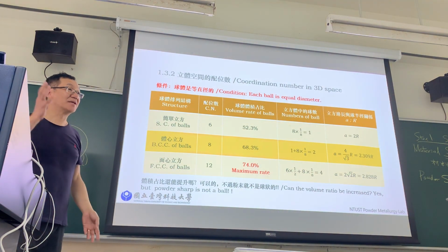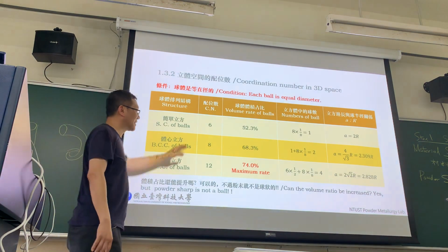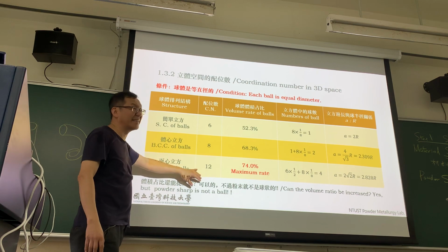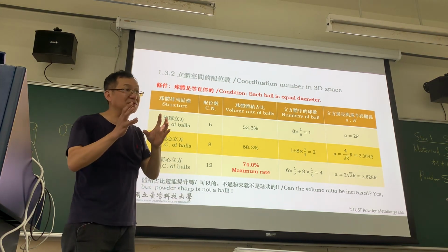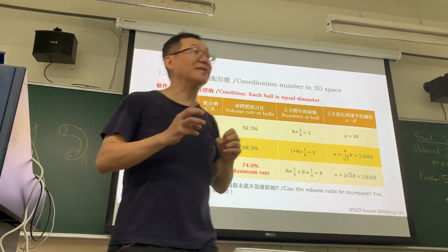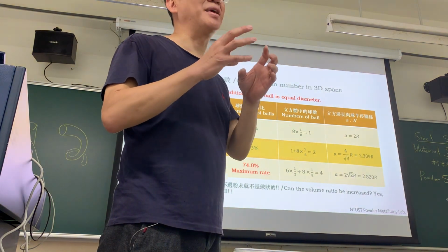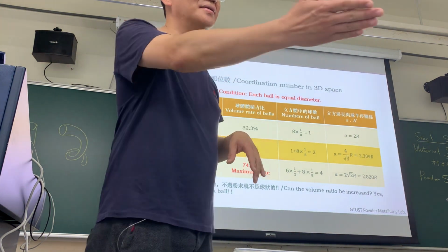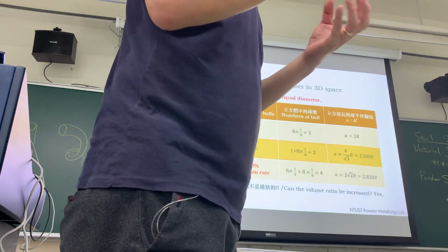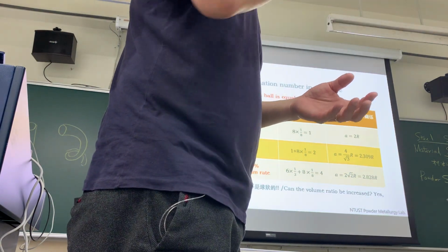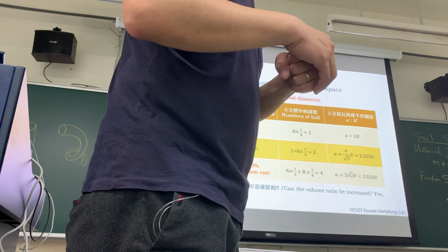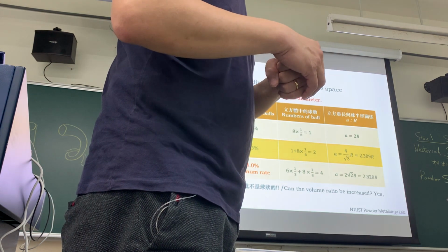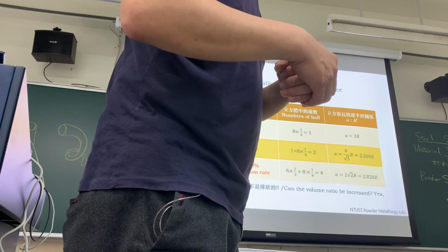For any powder, if you want to pack it more densely, the coordination number should be higher, and you can change the diameter. You cannot keep just one diameter. Do you think if you buy powder of only one diameter, is it expensive or cheap? Expensive. Why?